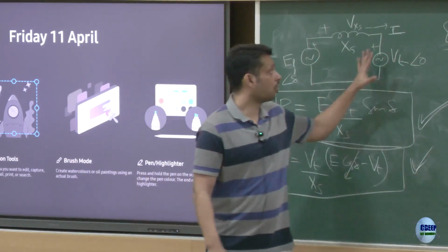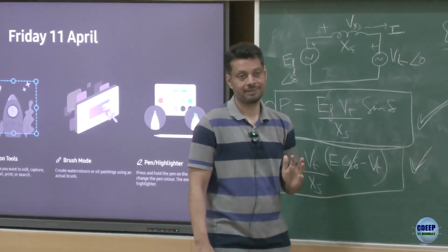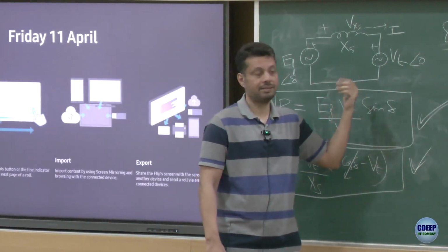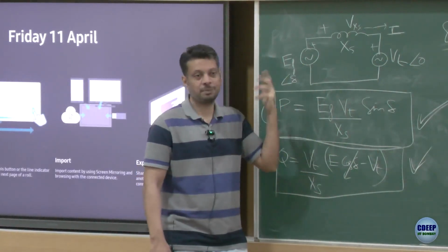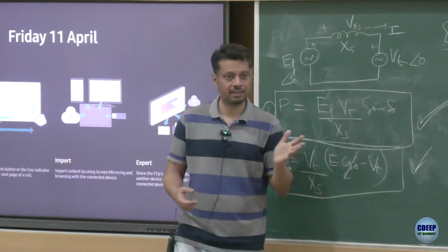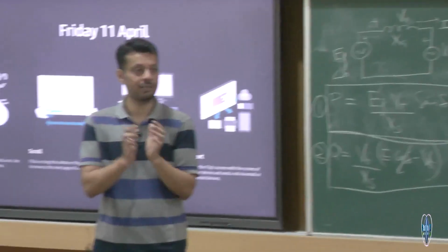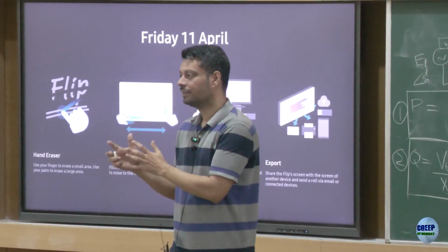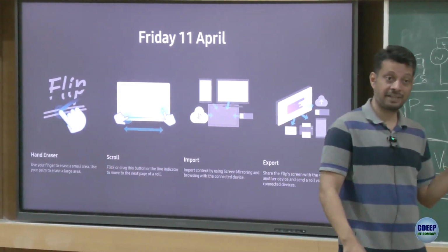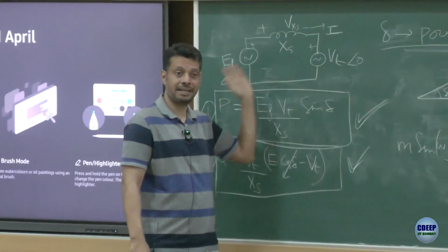Similarly, you have connected a lot of capacitors and suddenly all the inductive load turns off. Now who will absorb that Q? So you absorb that Q. So yes, you would like to minimize it. If you have a big power generator, you would ideally want it to produce the maximum amount of P, and Q should be somehow managed, but it has a flexibility. Whatever surplus Q is required or to be supplied, it can manage.